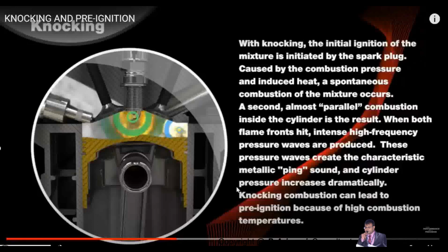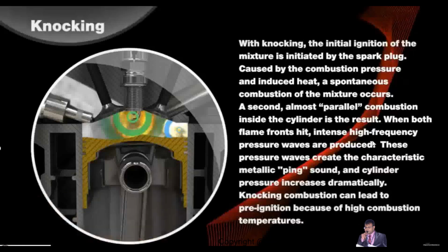I showed you some of the peak pressure, the temperature, the cylinder pressure gets overshot, and the knocking combustion can also lead to pre-ignition because of the high combustion temperature. See, knocking will lead to a pre-ignition, and vice versa also.